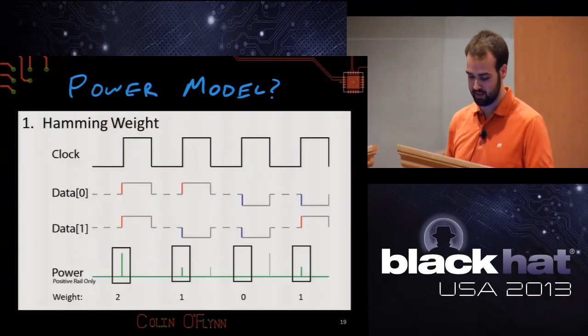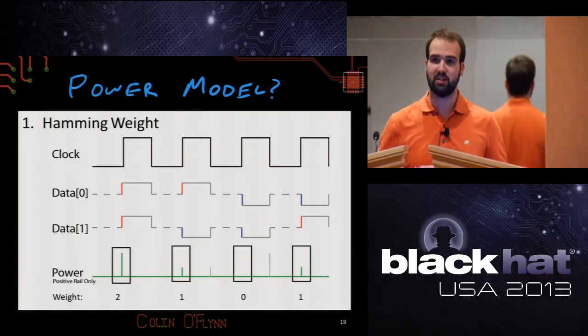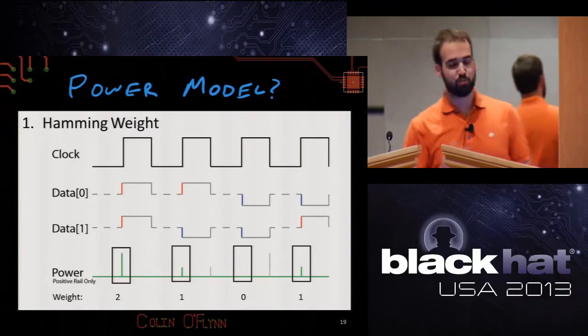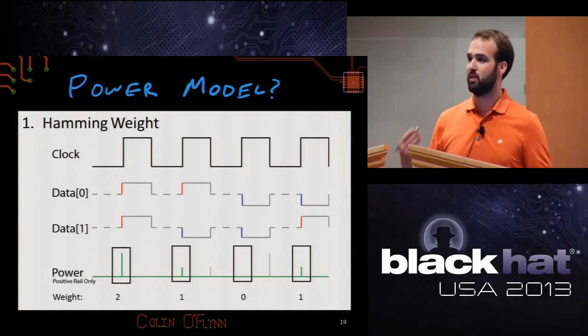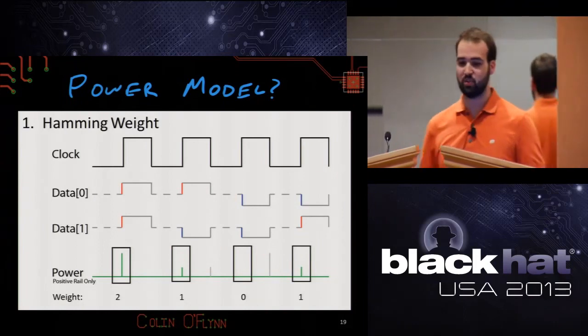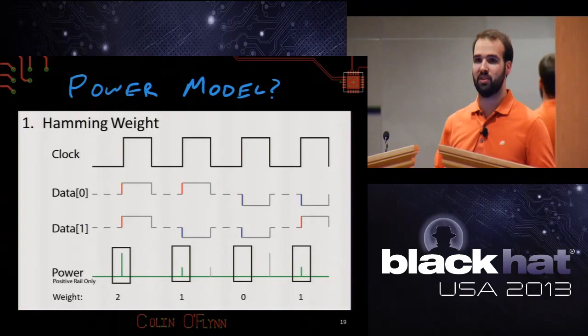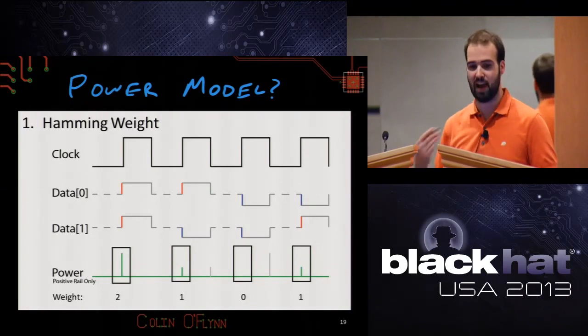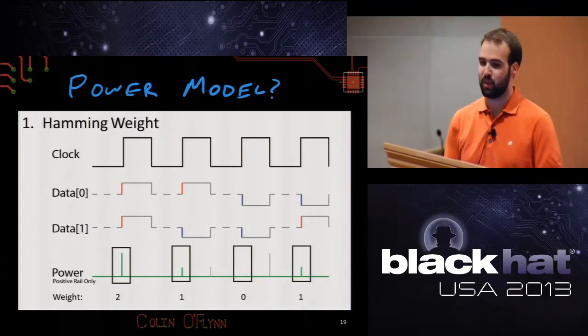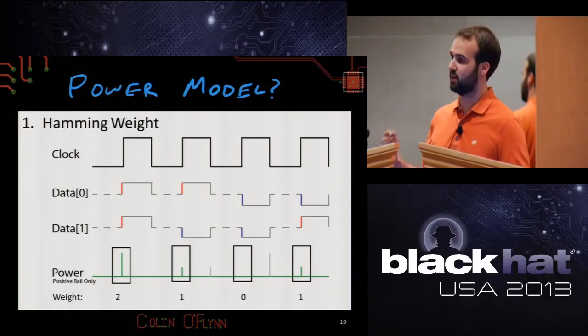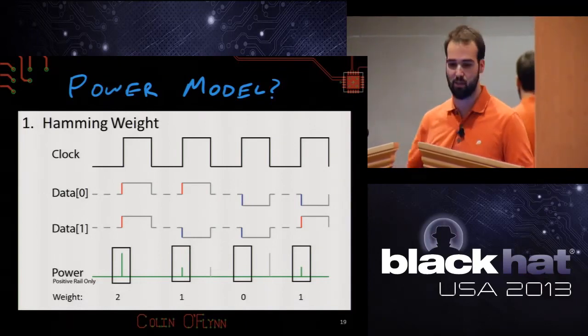So instead what they do is they always switch the data lines to a pre-charged state, which is effectively this intermediate middle state here in dashed lines. This pre-charged state is halfway between the 1 and the 0. The point being that when you want to switch the data lines to the 1 state, you no longer go from 0 to 1 potentially, you always go halfway to 1. So it's half the required power. So your worst case scenario is now much better than when you're switching all the lines from completely 0 to completely 1.